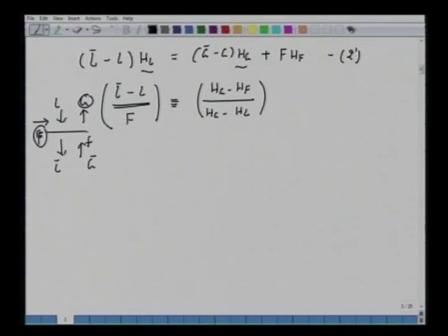All right. Whatever we have, this saturated enthalpy for the liquid phase and the vapor phase for this feed tray. So we have these ratios. We call this ratio Q. So this is the first time we are using this nomenclature. We are calling it quality of feed. We will see the significance of this.